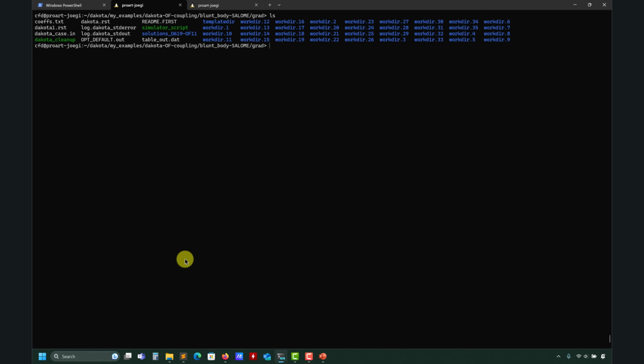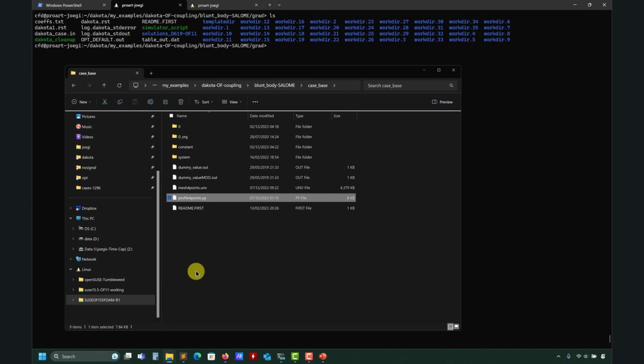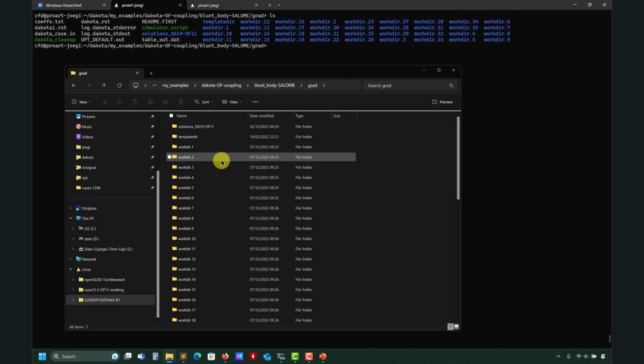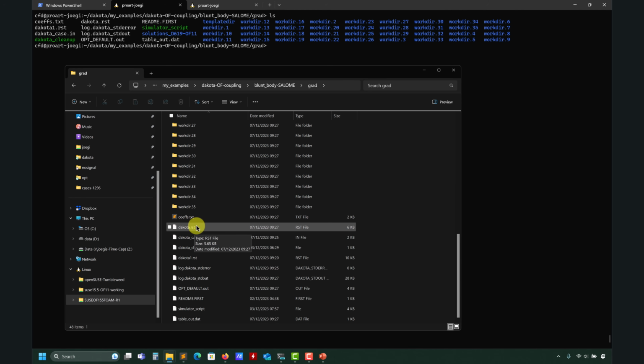And now what I want to talk about is restarting capabilities, because it might happen that you are running the simulation, and usually if you deploy this in an HPC center in a cluster, you have a time limitation, after 24 hours or whatever, it will stop. So your loop is not fault tolerant anymore. You want to have things fault tolerant, and this is the idea of having a restart file where you are saving all your sensitivities. That restart file is always safe. I don't see any reason not to save that. You can disable it, but by default when you launch Dakota, you always save that information in this file, Dakota RST. You have all the restart information there.